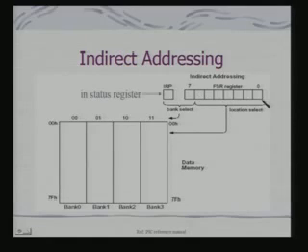Now once you have loaded the FSR register with this value, you need to access the INDF register. Once you access the INDF register, PIC actually uses the address in the FSR register to access the operand in memory. So you can see that indirect addressing in the PIC requires the use of not just one instruction but 2 instructions for specifying the address.